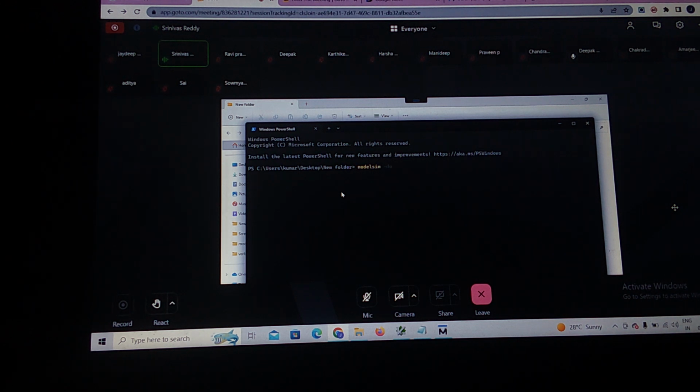What I want to do is do run.do. In my run.do file, I have all the commands. Correct. First, it goes through compilation, elaboration, and simulation; I put those commands in my run.do file. Correct.